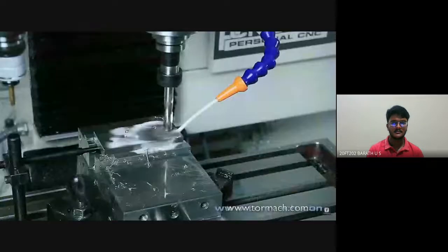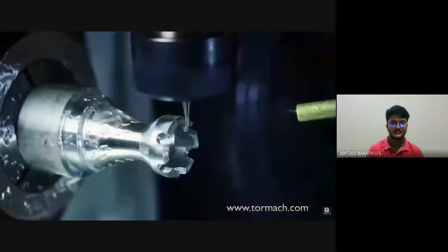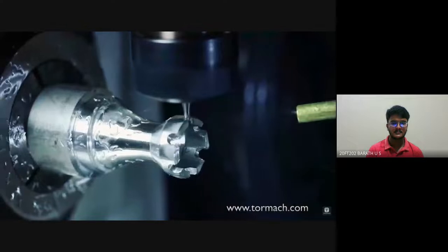Without coolant on high-speed steel, you run the risk of extremely fast tool wear or even the tool welding itself to your part. The stock you're cutting will change how you use your coolant as well. Aluminum is known to be a forgiving material because it's a soft metal, but that makes it quite gummy. So you're better off using flood coolant. Mist coolant will work, but the deeper your cuts, the more chips you accumulate, meaning more need for chip clearing.